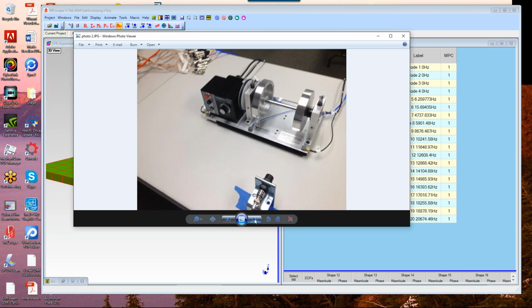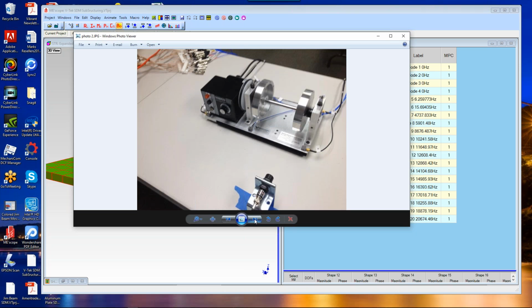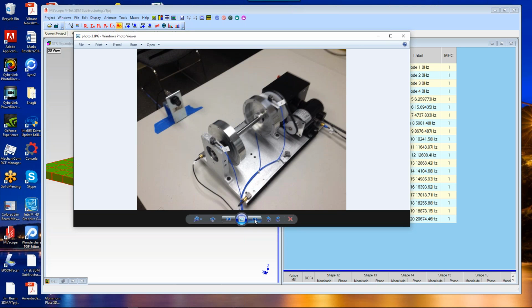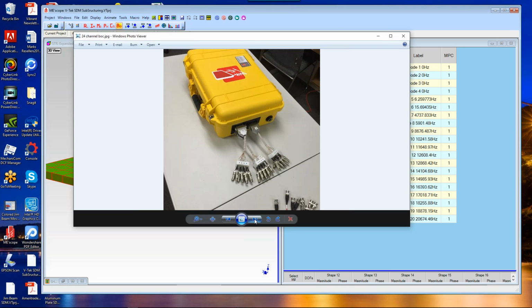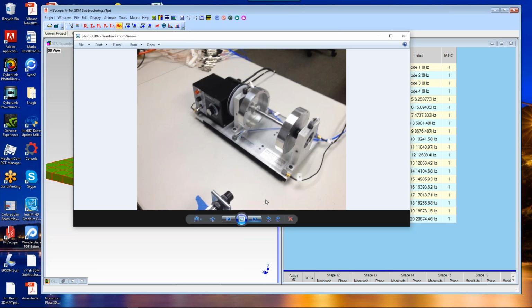So as the machine changes speed, it vibrates differently. It's sitting on some rubber mounts, so you could say that it's experiencing what's called soft foot, because of the soft mounting. A machine mounted in a factory would typically have rigid mounting. So here's the analyzer that was collecting the data, in one of our portable monitoring boxes. So that's the machine that the live data was taken off of.